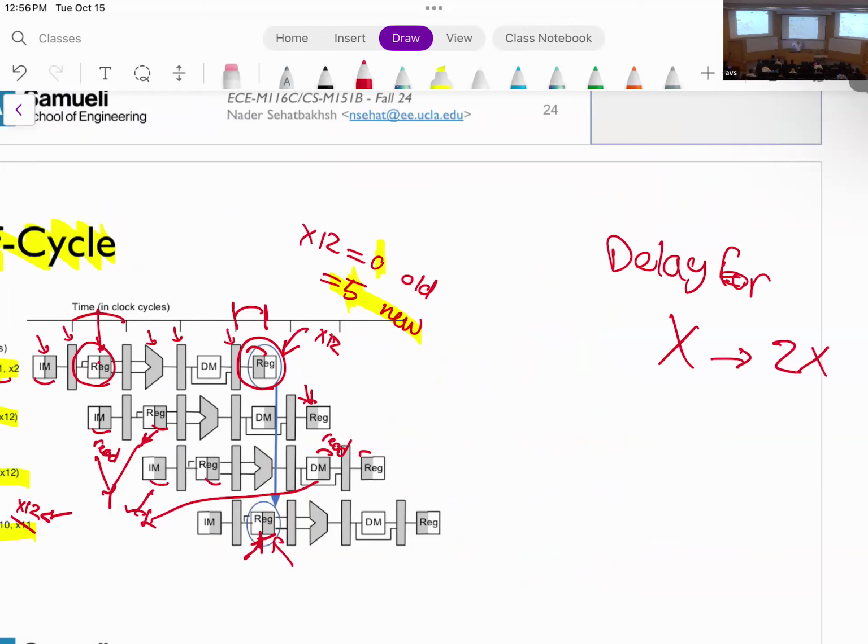In this way, I'll always make sure that the write happens in the first half of that clock cycle. And then I'm reading for the entire cycle. I start reading from the beginning because this is a combinational logic. But if I keep this line open long enough, at some point it will get the stable value, right? So if I make sure that my process of reading continues until 2x and my write happens in 1x, then I always make sure that my write is already completed and my read is continuous and reads from the second half cycle. Does that make sense?